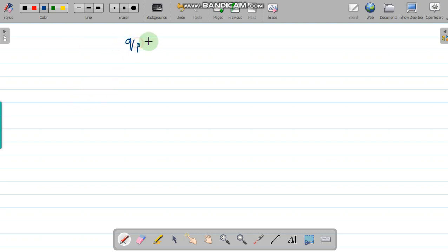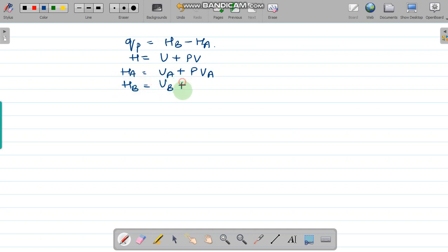So QP is going to be equal to HB minus HA. H is equal to U plus PV. So HA is equal to UA plus PVA. HB is equal to UB plus PVB.